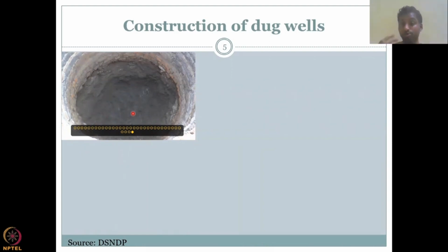All this you would have visualized. Now you know why they put it. They put it so that the surrounding sediment and loose soil doesn't fall into the well. But why doesn't this part of the well have that lining? Think about it. Once you go deeper and deeper, the soil is more intact. It's consolidated, and the pore space is less. Once the pore space is more and it's unconsolidated, it can move and then fall in through water also. But here, as you go deeper and deeper, you have less water and also less pore space to make that movement.